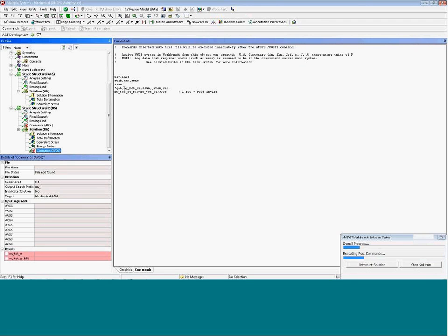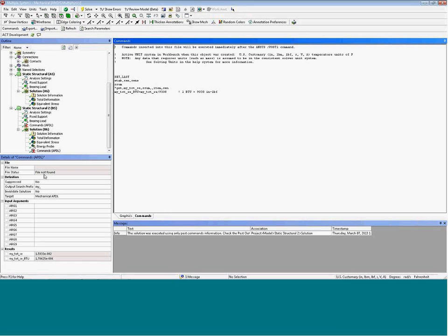For this parameter name, I'm specifically using MY underscore as the prefix, because if you notice in the details of the command block, there's a search output for underscore prefix. So long as we set up whatever the prefix is in here and make our parameters match, then it'll show up in the results down here. So you can see them, those show up in here. And you could check this box and make a parameter out of that. I'll come back to that at the end of the webinar.